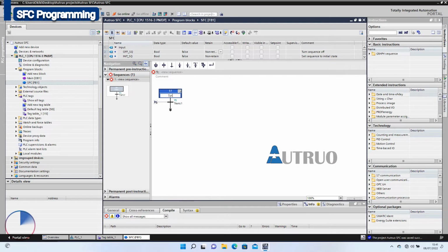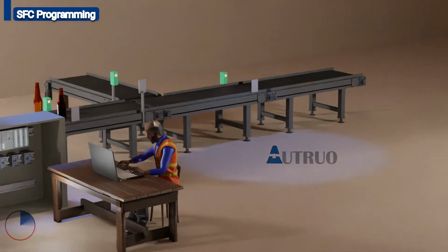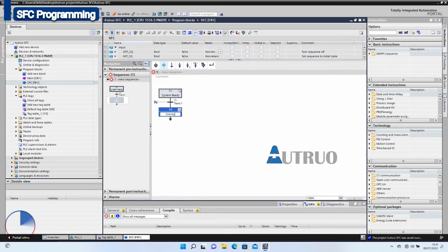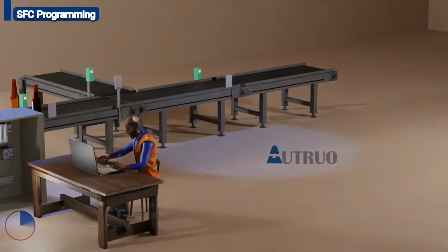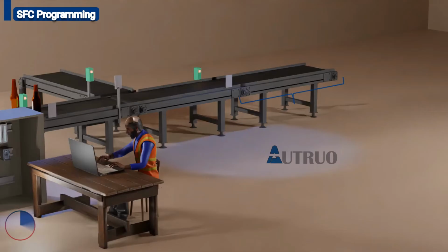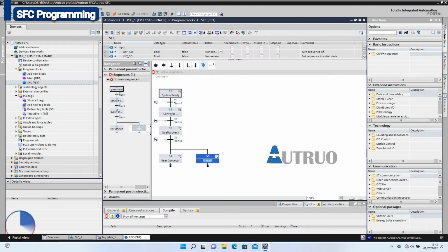The first one, which is S1, depicts a ready system, which means when the push button is pressed, the conveyor system will be on standby, and it is only when the conditions are met that the conveyor should start rotating. The next step is the system, followed by a quality check. Now in this step, the plan is to have a sensor that checks bottles that do not conform with the required height. While the last condition on this conveyor line is the rear conveyor, which is the adjacent conveyor. From here we'll move a step to the quality step. Now we will define the step as follows. The next step here is the discharge conveyor, followed closely by the bins.